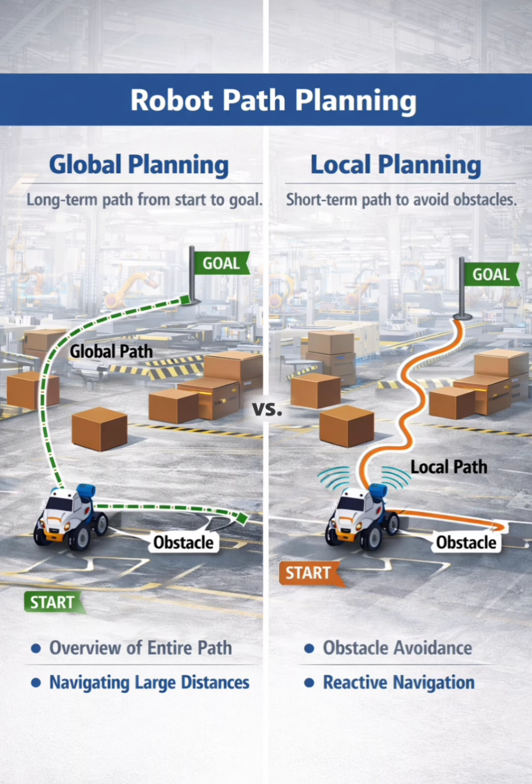For example, if the occupancy grid marks certain cells as occupied because perception detected shelves and boxes, the global planner searches through the free cells to reach the target aisle without crossing obstacles. Second, the local planner uses the latest perception updates to react in real time. For example, perception detects a moving person and reports their position and velocity. The local planner uses that to slow down, keep a safe distance, steer around them if there is space, or stop if the path becomes blocked.